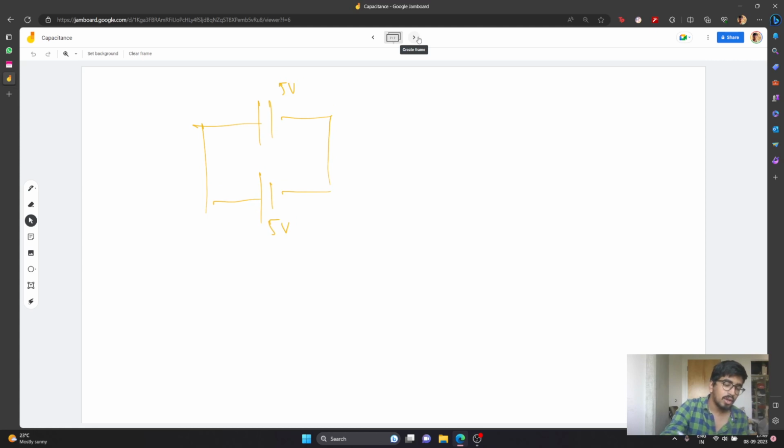But say this is 5 volts now, and this same capacitor is now connected to a new undischarged capacitor, right? So imagine what would happen. This is now a fully charged capacitor at 5 volts, but it is trying to discharge now because there is still a path, and at the end there'll be some charge redistribution, right? The positive charge will now try to flow, but it will store on the other one. So as the final condition, you would have 2.5 volts here and 2.5 volts here.